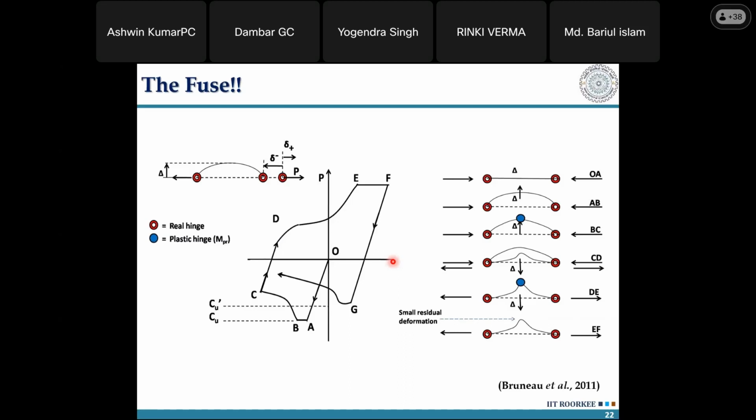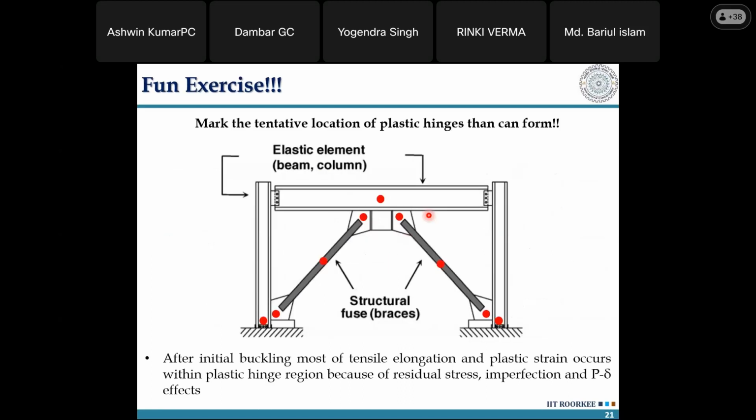One more thing: if you take 0.55 of C max and find the unbalanced force in the beam, you will get a lower vertical force in the beam. But if you go for T max and 0.2 C max as the value at the center of the brace, like let's say T max and 0.55 C max against T max and 0.2 C max, which will yield the maximum vertical forces in the member, the other is a lower value. In different tests, one particular test may have gone to 0.5, it may be a brace of lower slenderness ratio, but the code cannot give too much variation in its design.